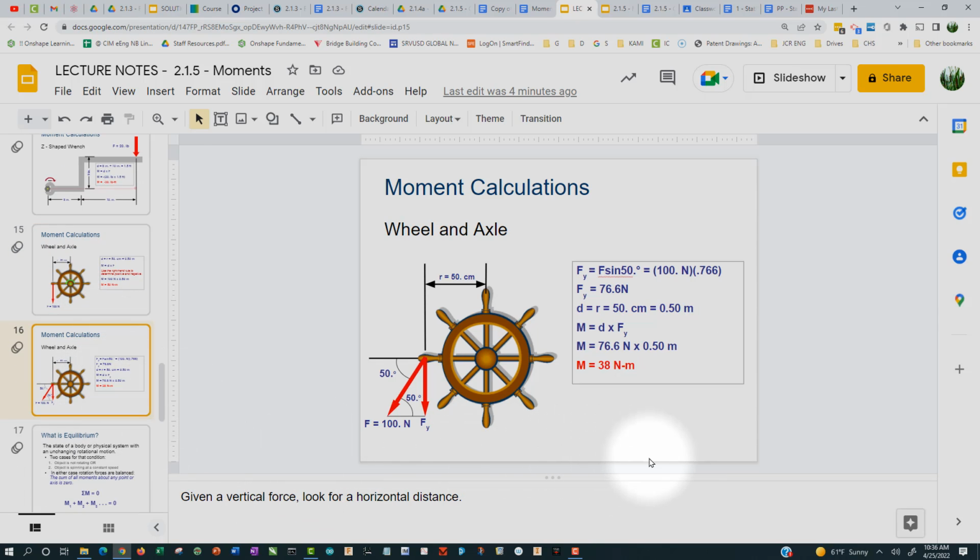What about if we have something here? So imagine that we pull out at an angle of 50 degrees with respect to the horizontal here, then what is the torque, our moment? Well, we have to find the projection of that force onto the perpendicular line from the moment arm. So you can do the trigonometry here. It's going to be 50 times the sine of 50 degrees.